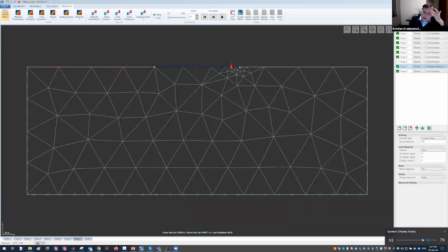Absolutely. So we have what we call the hardening Mohr-Coulomb model, but it's basically the same as the hardening soil model. It's exactly the same principles anyway. Then there are slight differences where we operate with an E50 and an EUR, right? Correct. That's a pretty good model, I think. And if that's what you're using already, then definitely, there's no reason that you shouldn't be using Optum.